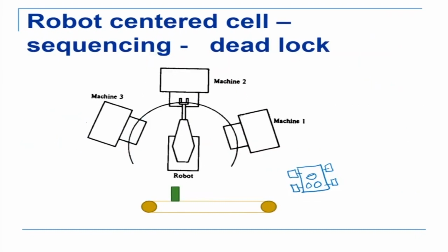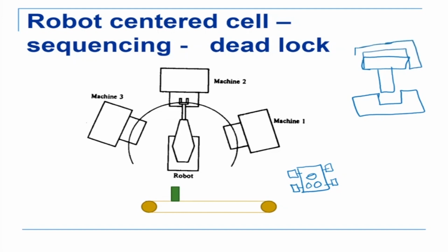But if you need more complicated kind of information going through, for example, if you have a robot which is assembling this part, and the robot is holding this part with a gripper and forcing it in, we have to measure forces and torques somewhere. If there is too much force, it will damage the part or damage the robot. So for interaction of this nature, there could be force sensors, torque sensors, and other sensors like vision or ultrasonic sensors checking distance from somewhere.